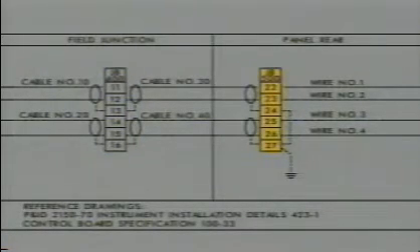The junction box is displayed as a rectangle with the top square marked JB and an identifying number. The connections are shown as squares. So electrical connections in a junction box are shown as squares. The numbers inside the squares are the connection point numbers. A note tells you that cable 10 goes into junction box 400 and cable 30 comes out. You'll also see wire numbers noted. This information can help you isolate a signal line if there is a problem.